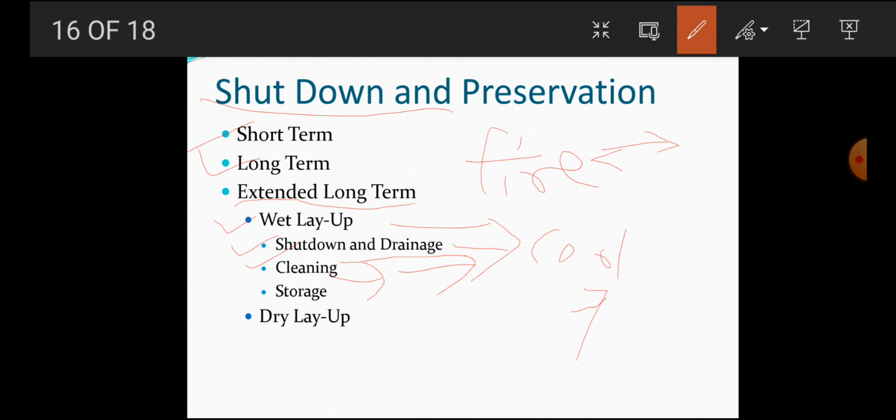Then replace water gauge glass, clean pressure gauge glass, fire eye, ignition orifice, burner, etc. Then we need to grease and oil. Grease and oil all pump, fan and burner fittings. So all the fittings need to be greased and oiled. Then check fuel oil level, add fuel oil, additive and have all tanks filled to top for summer storage.